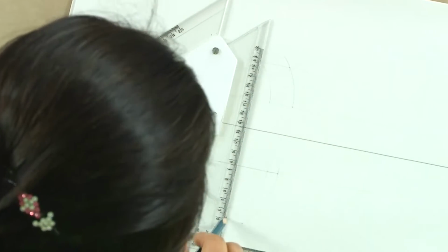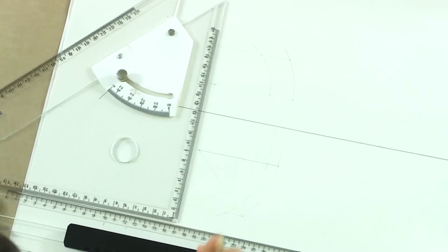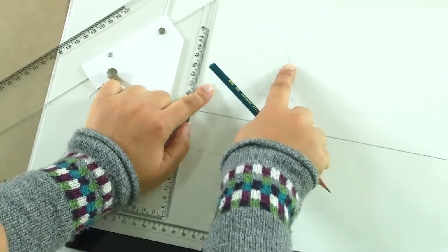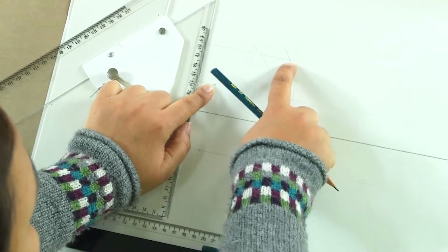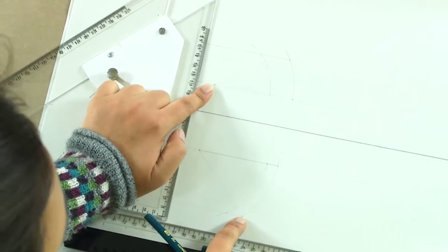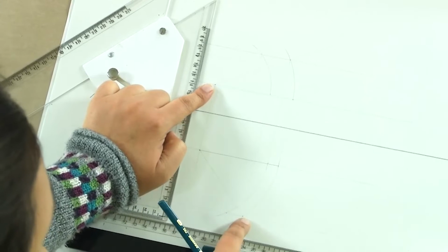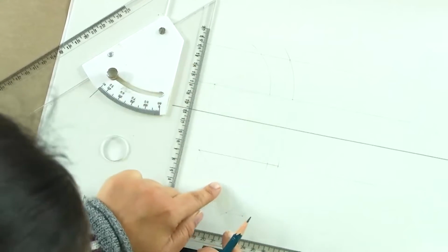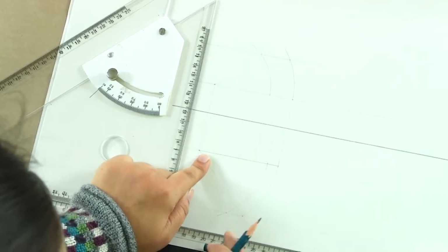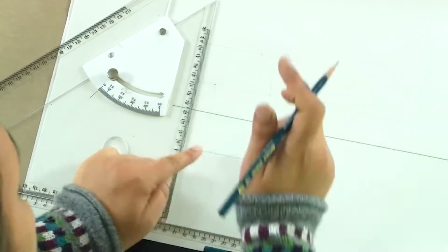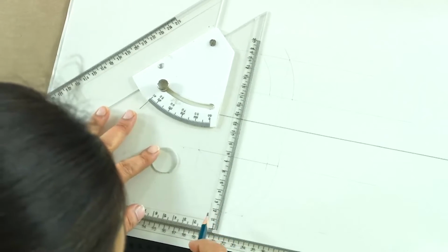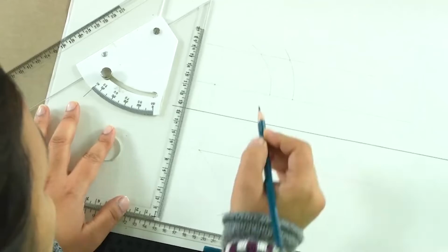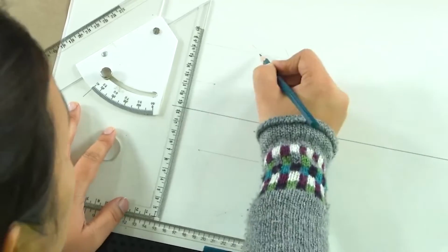in a straight line, because now here what we have done, we have taken the projection of this line which was inclined at HP to a locus, to a line, a path which is obtained by inclining that same line at 45 degree to VP. Or we could do it in the reverse manner, and if we have drawn it correctly, we would get the projections in the same line.